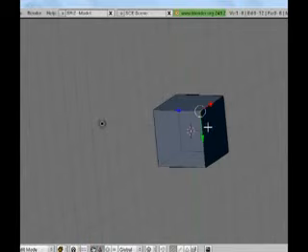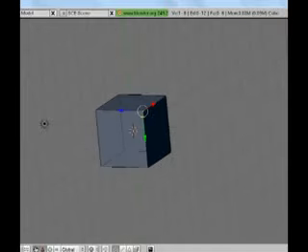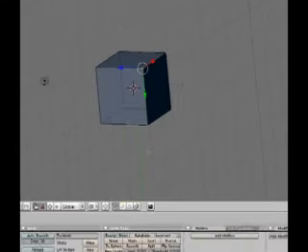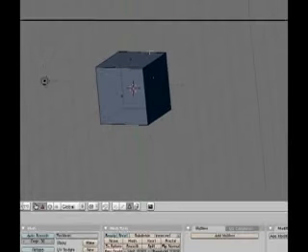And then Blender allows for quite a few undos. And what I want to show you now is extrusion. What extrusion is, it's kind of like grabbing and stretching, but it actually creates more vertices and faces and edges. And usually you'll do extrusions in face mode, but not every time.